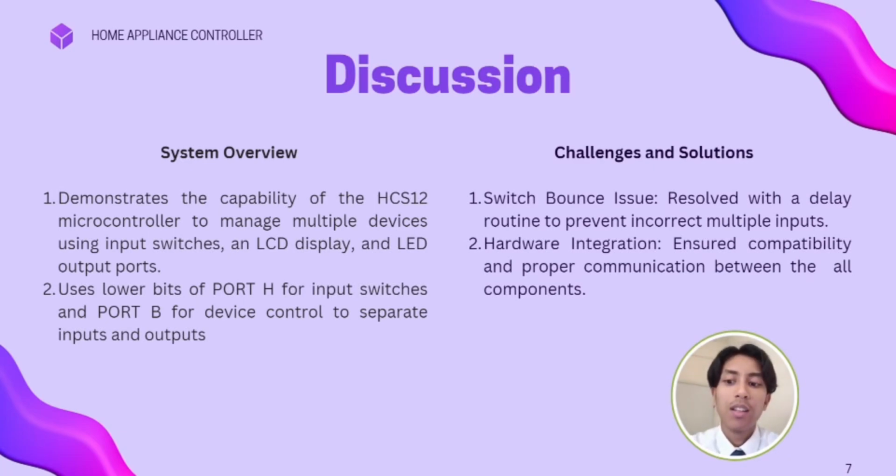By adding a delay routine in code, it effectively filters out these unwanted bounces. Second is hardware integration. To ensure all the components of the HCS12 microcontroller, LCD, switches and output ports work together without any communication issues, we need to always troubleshoot the coding so that it will work as we wanted.